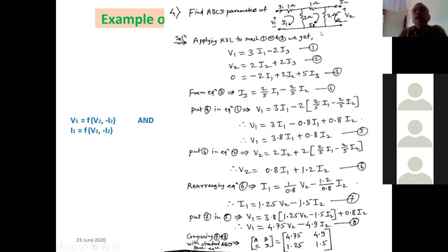Now again you can find that this pi network is there of 1 ohm, 2 ohm and 2 ohm. That is, they are forming the delta. You can convert this delta into star, and then you can add it with other resistances so that it will become a T network, and then you can solve the problem. Or if you will not convert delta into star, even in previous numerical, you can tackle it by this way.